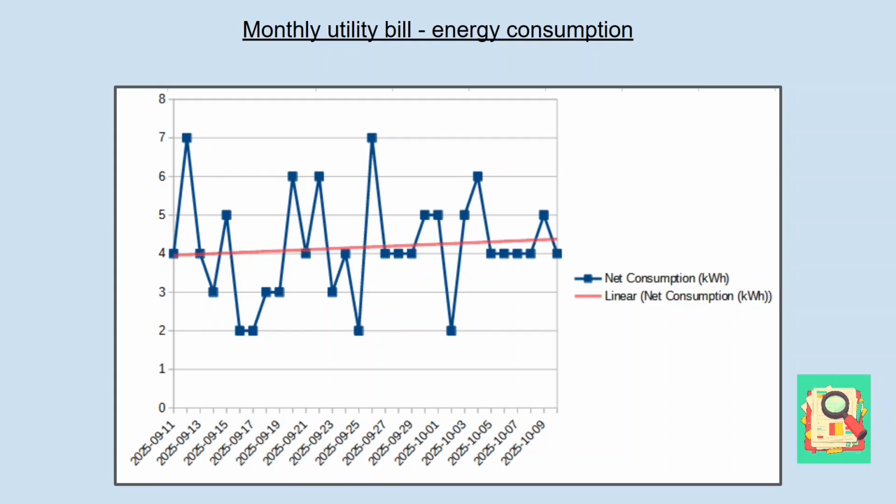From the graph, we see that the average energy consumption is between 4 and 5 kilowatt hours on a daily basis. In order for the energy consumption graph to be useful in sizing the inverter, the solar panels, and the battery, it has to have a higher resolution. What I mean by that is that the energy consumption has to be on a finer basis. So on an hourly, half-hour, or ideally a 15-minute basis. The 15-minute basis is what the utility companies use to charge commercial accounts.